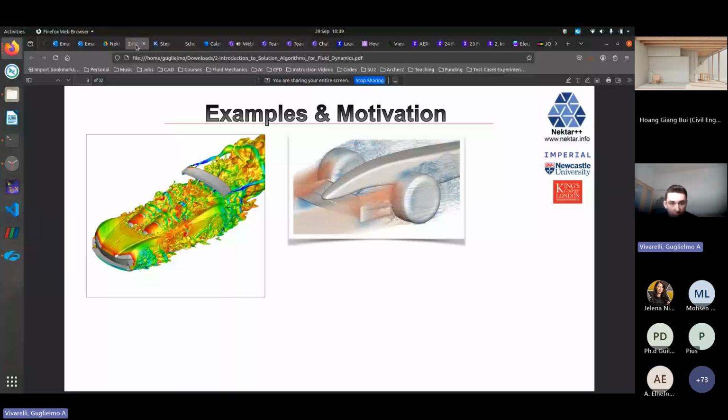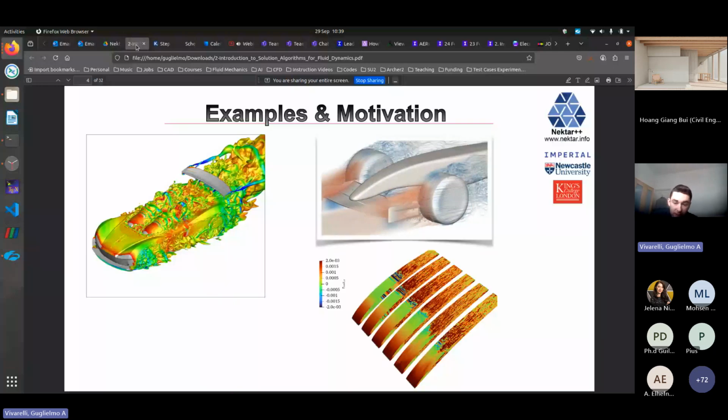There are practical cases where you would go for incompressible solvers, even though it doesn't really make sense out of common sense. And this is a compressor on the bottom right-hand side. The reason why I went for that particular solver is because the experimental data was in incompressible range. And this allows me not only a saving in terms of number of PDEs I'm solving, so you go from 5 PDEs to 4 in incompressible range, but because this particular configuration is a 2D configuration extruded in the spanwise direction with periodic boundaries, I can also use a Fourier expansion, which adds further savings.